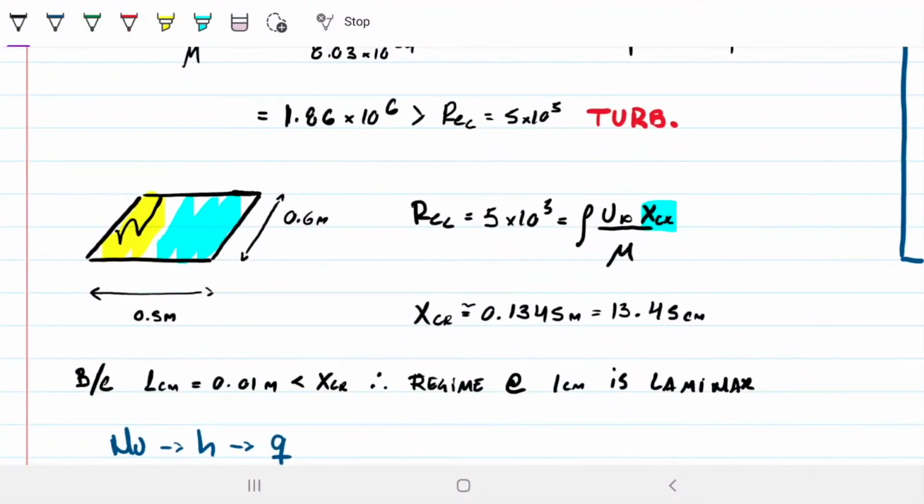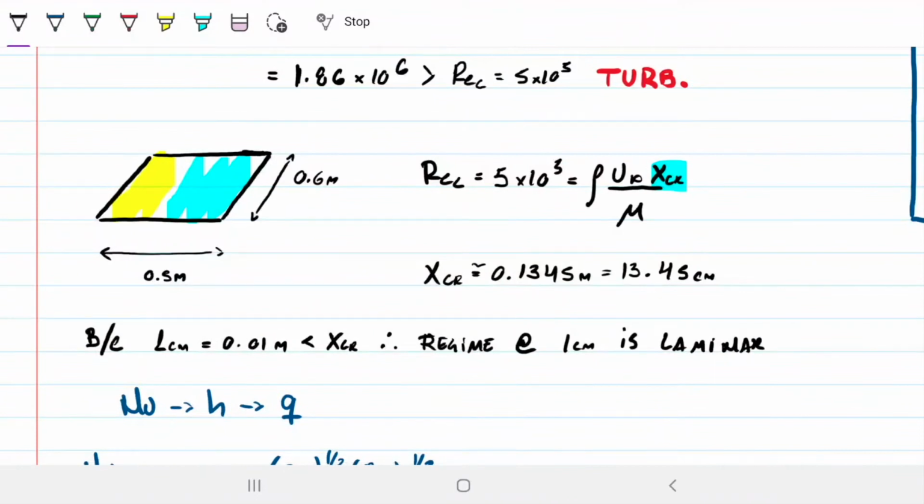So that means that I need to grab the local heat transfer coefficient on every single stretch of this yellow portion here, sum them all up, so that I can have the final heat transfer coefficient for all this portion here. And if I sum up every little portion of heat coming out of every little single strip that I just drew here, then I'll get the total one.